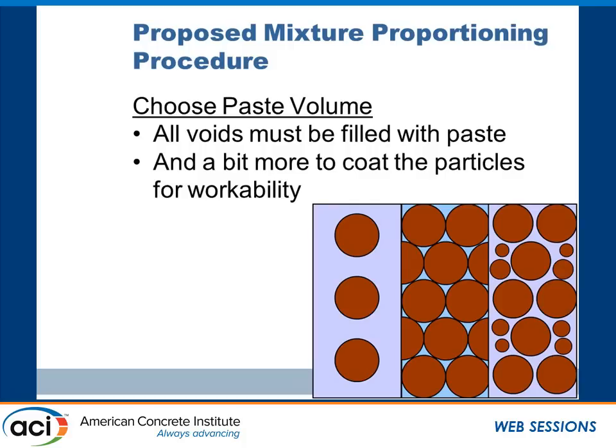I'm an engineer. If you tell me something's a bad thing, I'll take it all out. So here I have very little paste and lots of aggregate. That thing's not going to shrink. Is that a good mixture? Why? No workability. And the other issue is there's actually no glue in the aggregate touching points, so your strength's actually going to go south. All right, so this is why engineers make the big money, is that we have to fight with learning the black art of balancing contradictory signals.